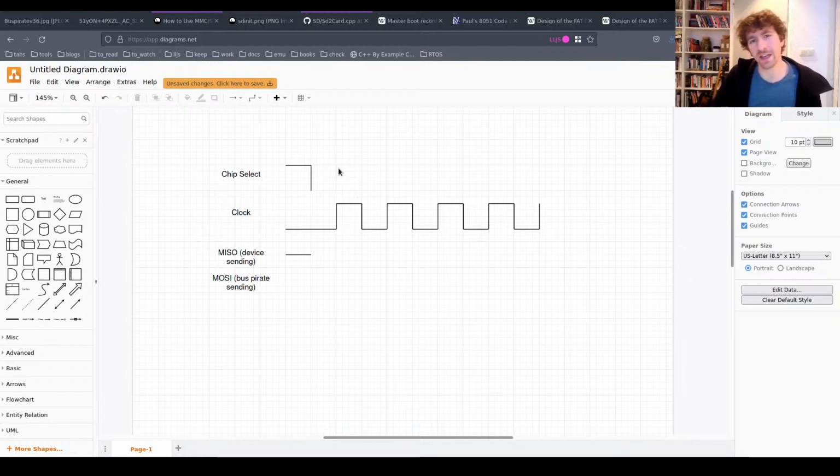So yes, SD card, if you run it in the native mode, and actually also in the SPI mode, but in the native mode at high frequency, SD can actually do 1.8 volt. But by default, when you run SPI mode, you're not running at high frequency, you're running at quite low frequencies, and then you use 3.3.